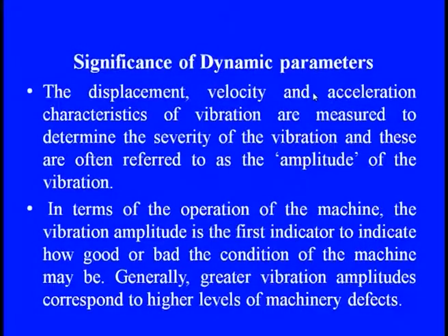So, first, the significance of the dynamic parameters. The displacement, velocity or acceleration are the key parameters needed to characterize the vibration. We want to measure them to determine the severity of these vibrations, and these are often referred to as the amplitude, because whatever the amplitude of these three quantities is, we generally call it the amplitude of the vibrations.